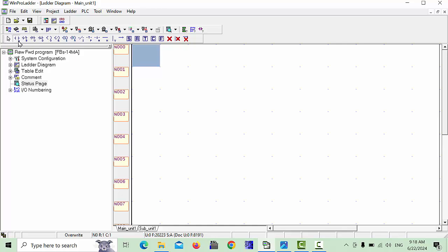So first of all, I will take my 1 bit, starting from M0, internal memory relay. Because when you design a complete program in a PLC, you can make it serial-wise. Start from M0, or M10 or M20, M30, anywhere you can start. I will start from M0, and I will make names for the execution of my program.